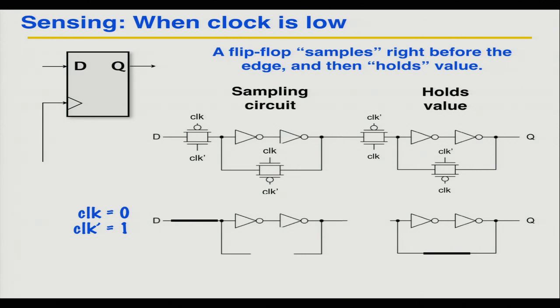So that's a tricky, really clever circuit that we can use to provide the edge-triggered behavior that we want, by using a master and a slave, or two latches back to back.